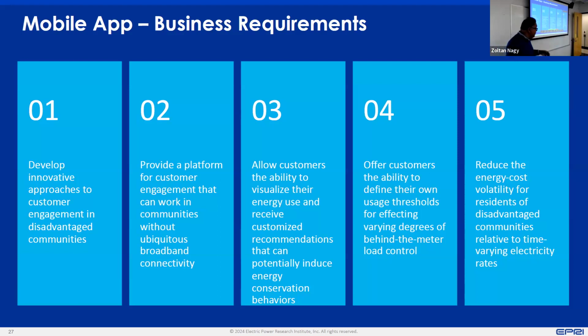What it means is that if you are confronted, first of all, with something like requirement number 4 that says they should be able to opt in and opt out of this automated load management at their will, now you need a mechanism in your MPC controls or whatever control algorithms you're developing to take that volatility of participation into account. You cannot assume that people are participating at all times. So there has to be some of this stochastic nature built into your algorithm.